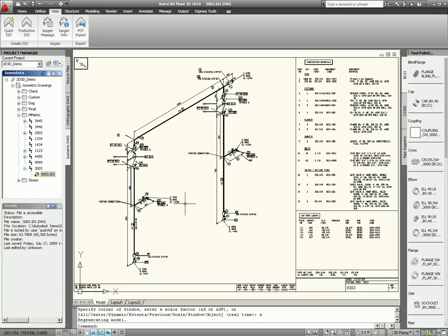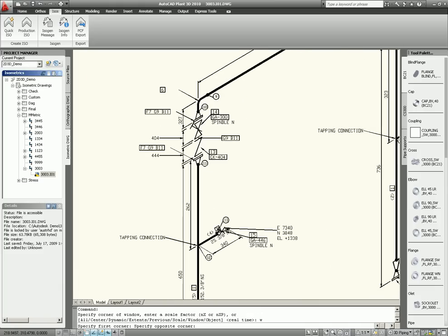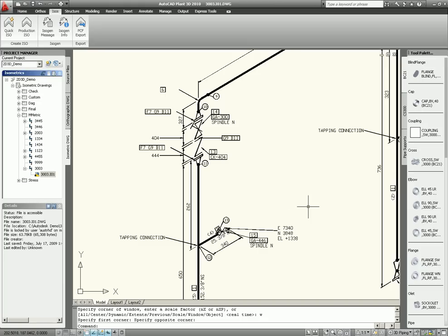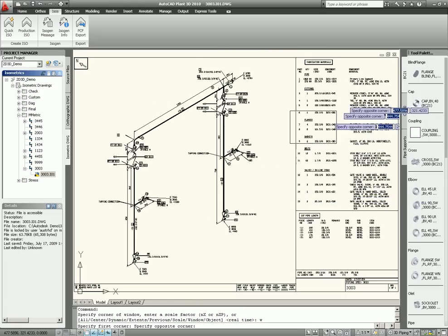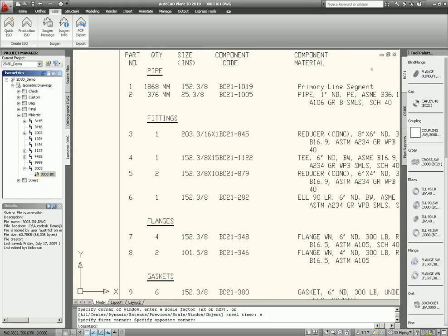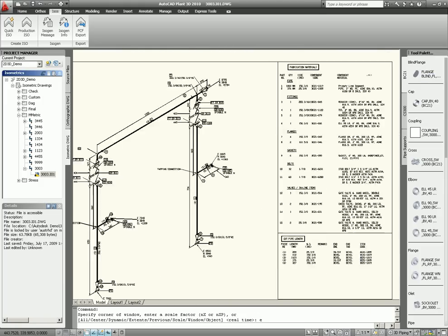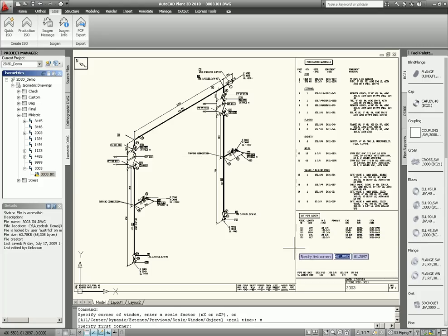As you see, this is now a production ISO. In mixed metric, it gives you tag numbers on the valves and weld numbers and tag numbers for the bill of materials and so on and so forth. It also gives you a complete bill of material and the part number for the component, and of course also a cut list.